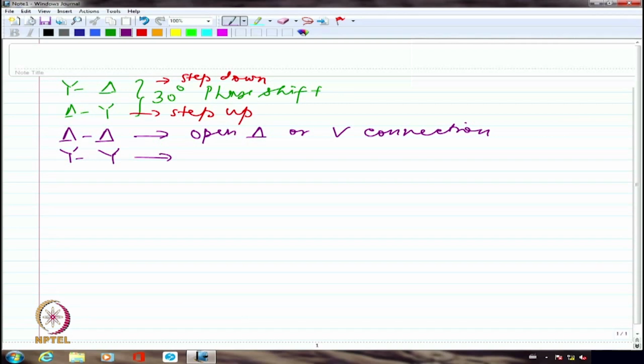So the current will have the fundamental component, that is the 50 Hertz component, which is sinusoidal in nature. Apart from that, it will have third harmonic, fifth harmonic, seventh harmonic, and so on and so forth. If there is a third harmonic component, which is one of the dominating harmonic components in the magnetizing current, that will not find a path to flow out of the transformer winding.